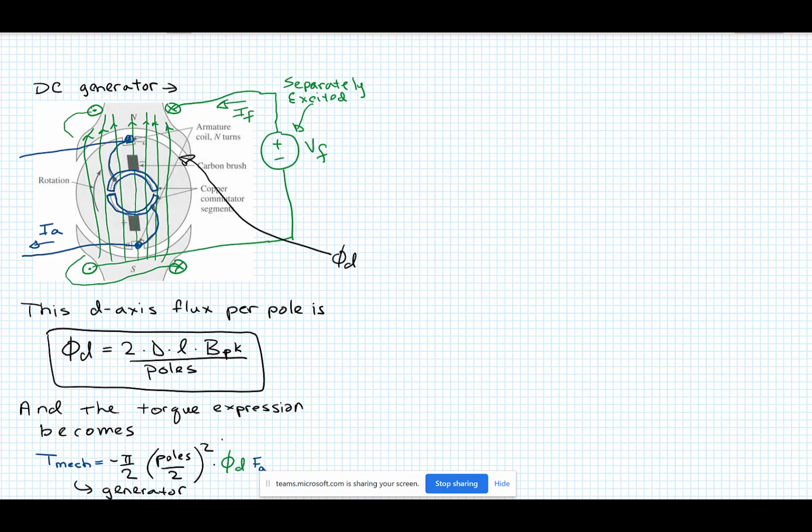You've got your winding, just like we talked about before, on the field, wrapped around this yoke, and so you've got these green lines, which are a flux flowing across the gap. It doesn't show the rest of it, but it's going to go back and flow through the other sides of the stator core back to here. So there's all iron around here. It's like you've got a back iron that the flux has to flow into.